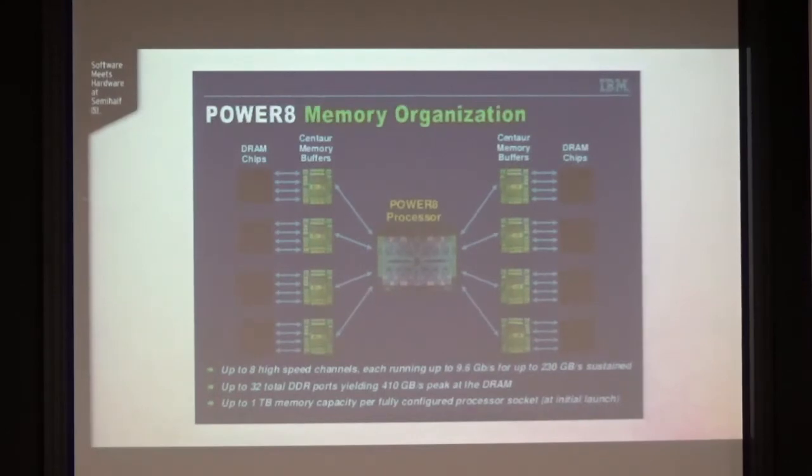IBM decided to provide a level 4 cache between DDR and the CPU itself. By between, I mean literally between. The L4 chip is a physical chip located on the PCB, between the DDR and the CPU interface. For all of you familiar with Intel 386 or some other ancient times, there's a similar approach which IBM implemented in the POWER8. If you're asking me what is the impact on performance, well, I don't know.